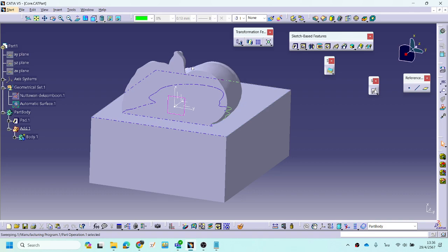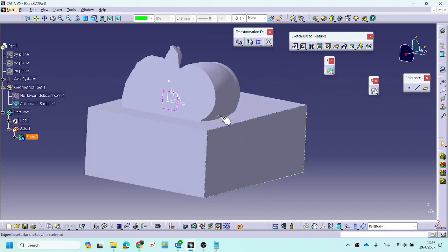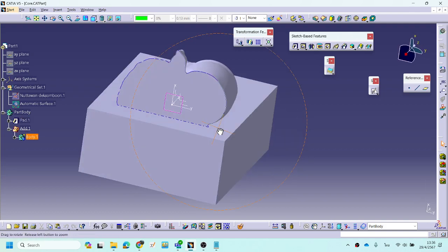The cutting tool can move around the area if the table of the 5-axis CNC machine rotates and brings this area up, and the cutting tool can cut around that area. This is the benefit of the 5-axis CNC machine. Undercut can be cut, right?